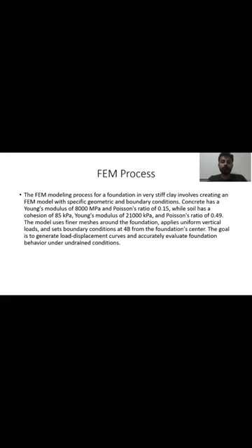For stress strain analysis, to determine the stress and strain characteristics, a stress path based on the shearing stress will be considered. The mean effective stress and the shear stress at significant states such as the starting point and the failure point will be calculated. From these values, the corresponding volumetric strains and the shear strains will also be determined.